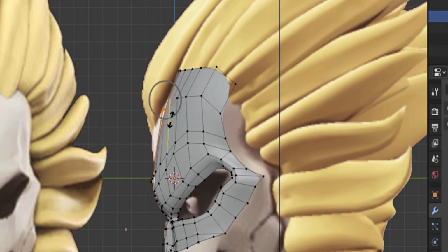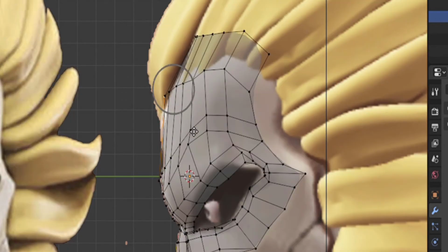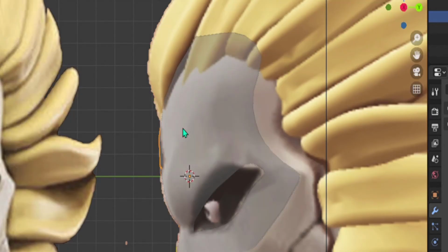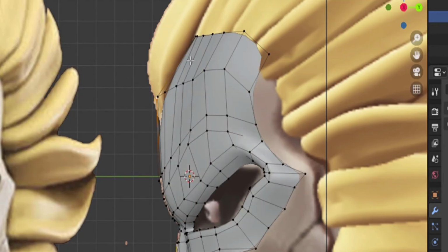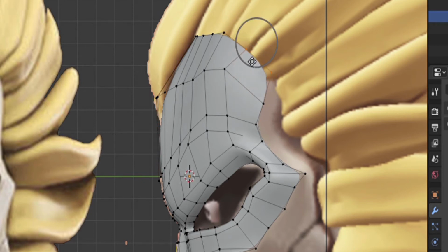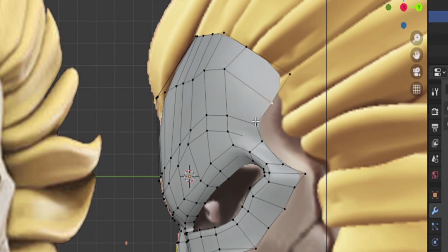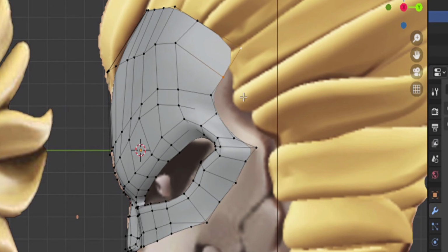We can bring those down a little bit. And let's bring those out to about there. Just so we get a more rounded shape, as you can see. And then here we can come in here. Obviously bring these down. Like so. And now let's just extrude these faces here. So let's select these two edges, extrude down, let's rotate that, then extrude one more time, and we can fill this in. So select them and press F. Select these and press F.